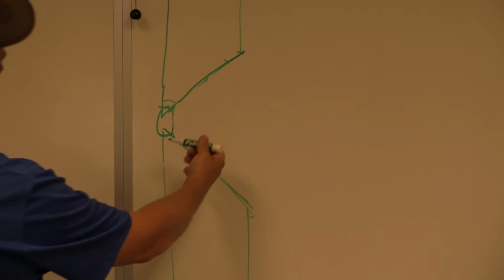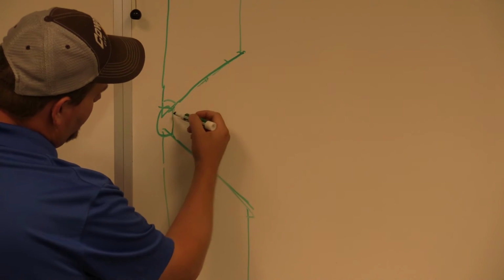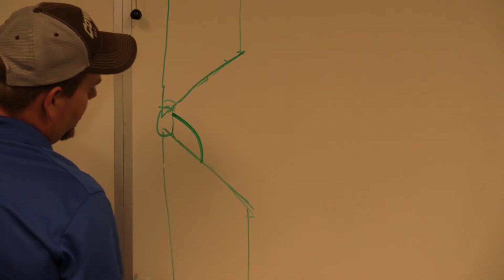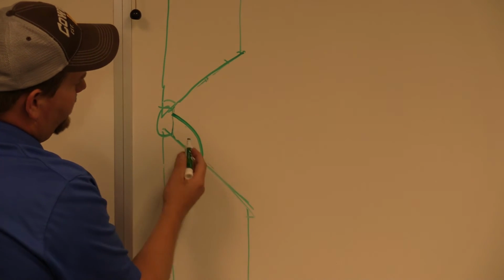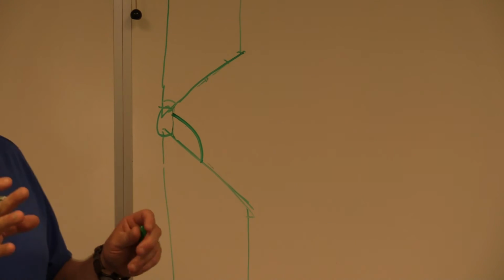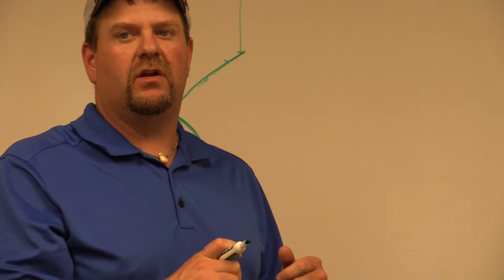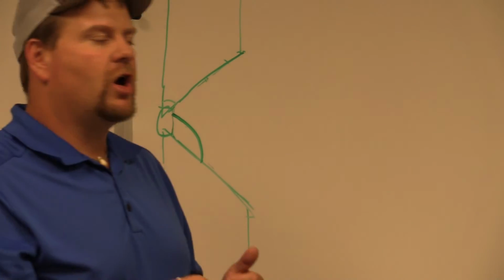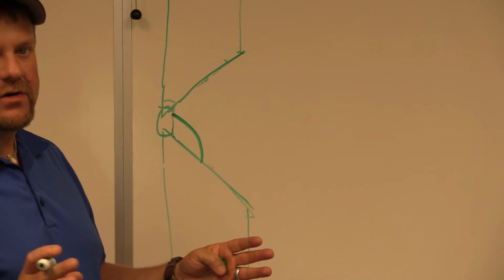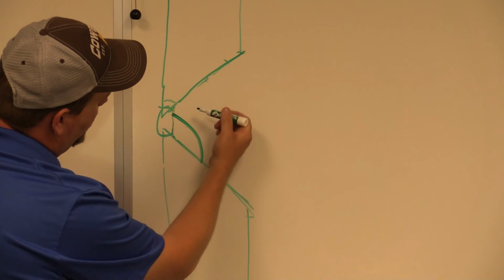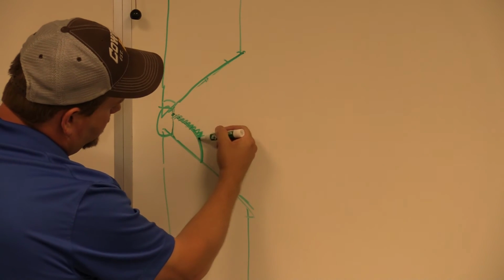So we brought our grinder in and cleaned it up here. Then our next weld pass we're going to put in from here. Say we weld from here to here, okay? Now if you notice, this gap right here is going to be a little bit rough. So again, in gaining the experience to be efficient and save time within our job, do I need to grind this entire weld back down? Not at first. But say I want to come in here and put a weld pass in from here to here. I'm going to grind down from here to my high point.